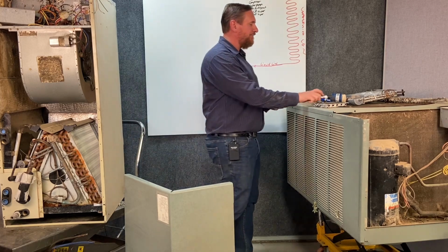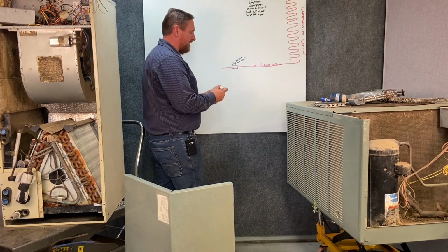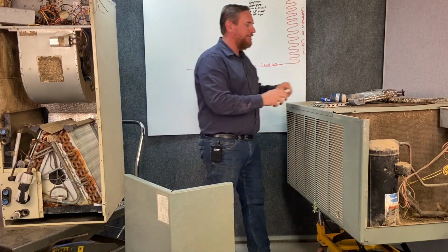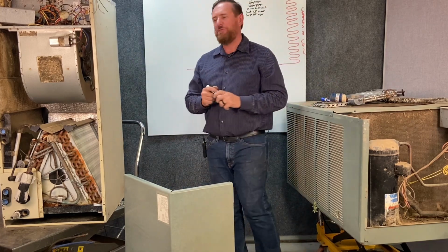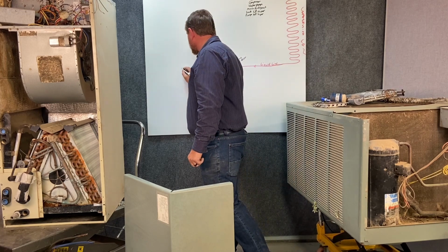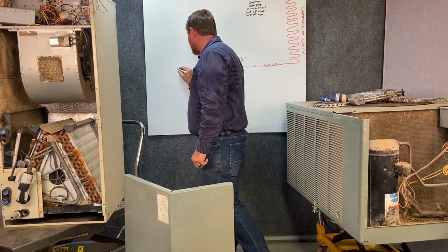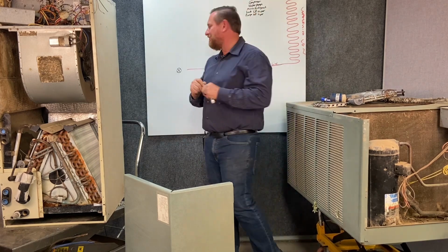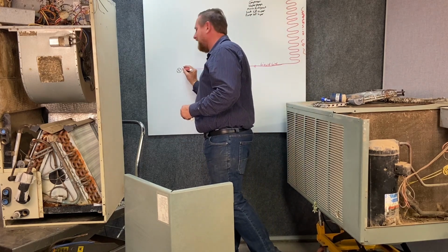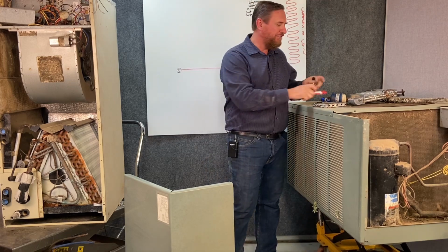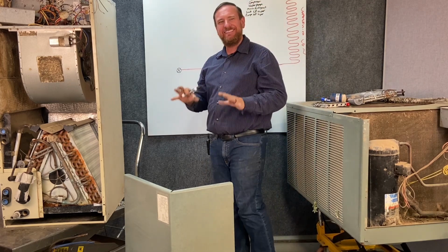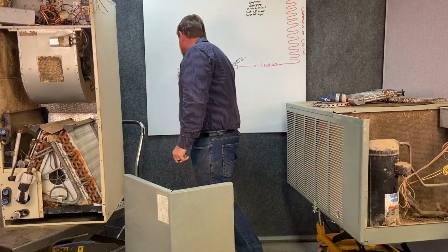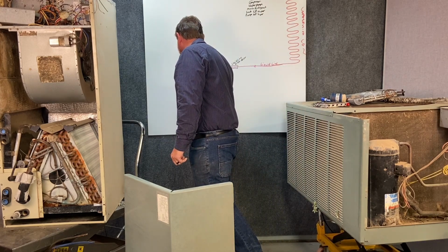So we're going to continue our refrigerant into that filter dryer, out of that filter dryer, and we're going to come to our next component. And our next component is a key essential part, and it's drawn with simply a circle and an X through it. And this component is called our metering device. Again, we're going to go into more detail about all these components. This is our most basic refrigeration cycle, but this is our metering device. So I'm going to write over here metering device.